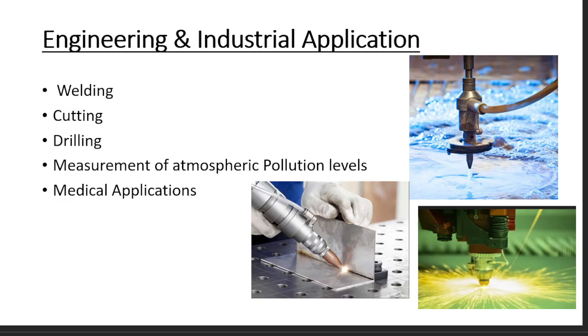The metal at the line of contact melts and solidifies after cooling, which sticks the two plates together. This is the welding process diagram of the laser. Laser welding is commonly used in automobile, shipbuilding, and aircraft manufacturing industries, using Nd:YAG laser and CO2 laser.